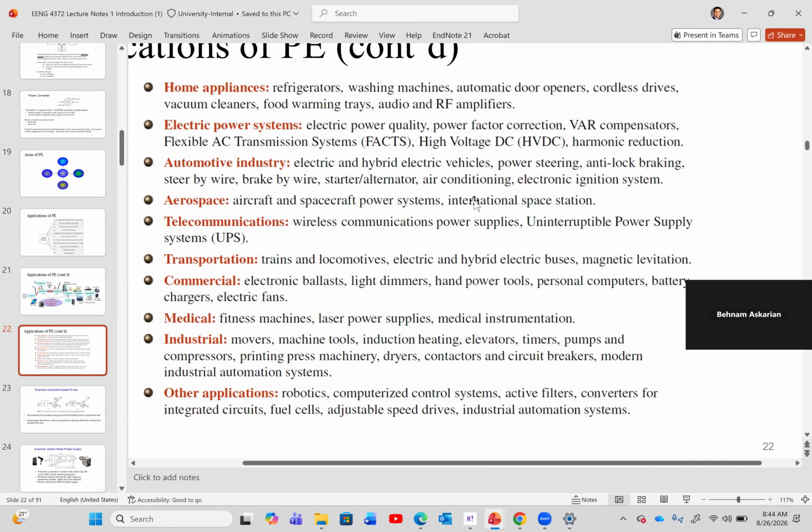Yes, some of them are beneath the floor. Some of them are actually in the rear. Almost all Toyotas that I've seen have the 12-volt battery in the trunk. The reason they put it there is that sometimes it's closer to the hybrid nickel battery. You don't need it to be close to the engine or the alternator. You can put it anywhere in the car, so they usually put it in the rear, which has more space. For EVs, some are in the front, some in the rear. And when it's in the rear, it's actually safer as well, because if you have a crash, you don't have that acid floating around.